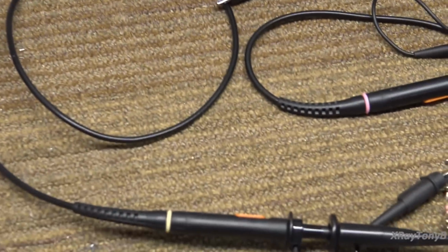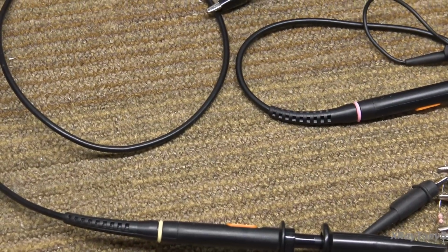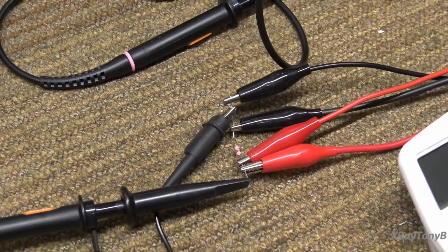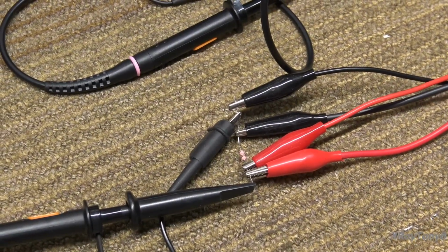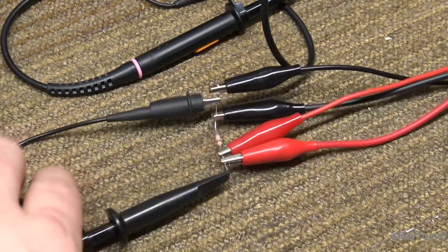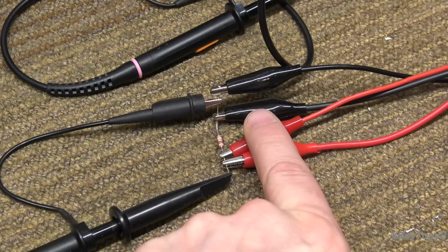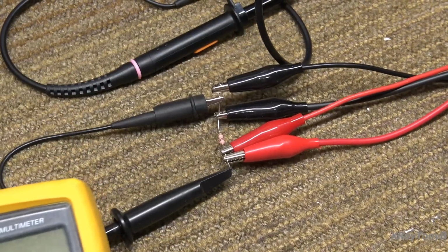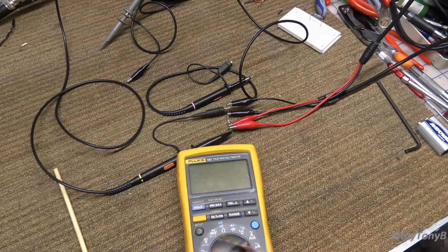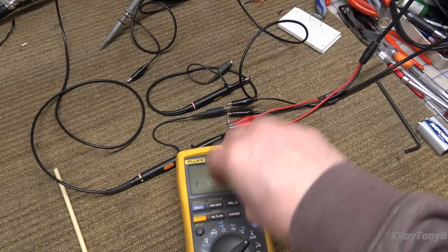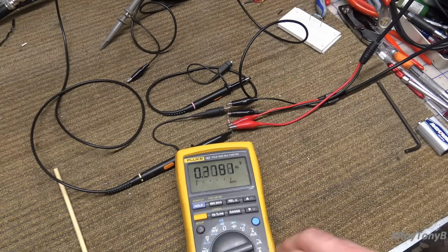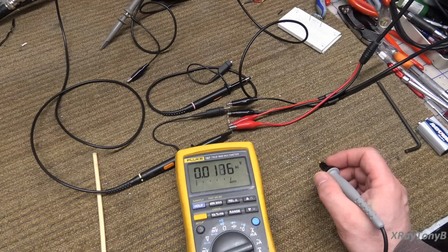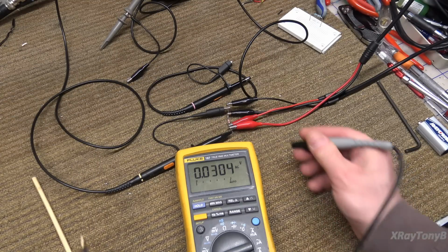And I had the lights off so we didn't get glare on the screen. And you can see right here where I have this connected across this resistor. And it doesn't matter about this resistor right now, but you can see here's the AC signal coming in. This is our voltage. And here's our probe to our oscilloscope. And let's move our meter in here. And let's turn it on to AC volts. So we're set to AC volts right now. What do you think it's going to say? Is it going to say 2 volts? Or is it going to say 4 volts? Let's measure and see.